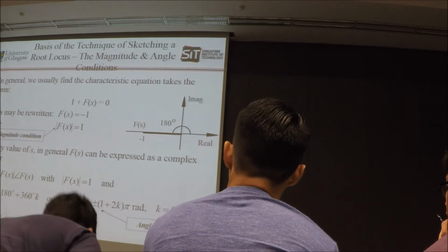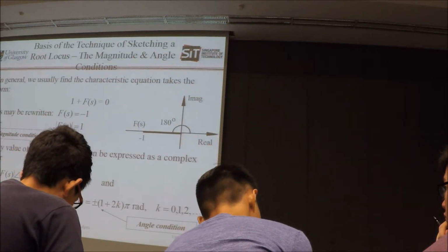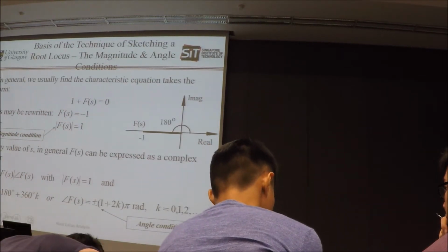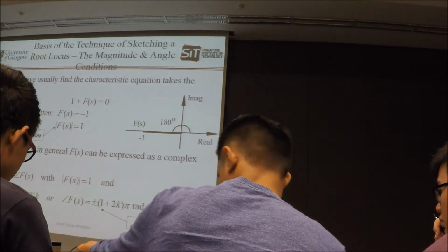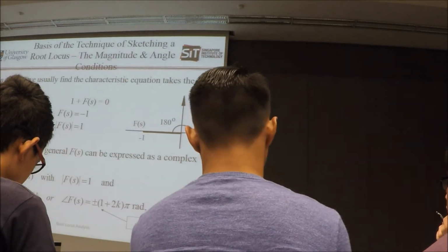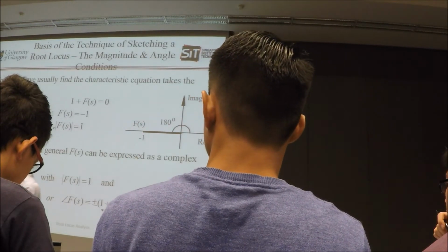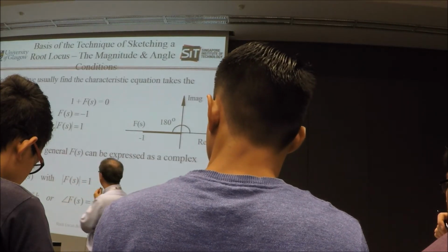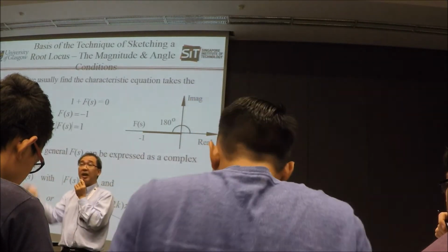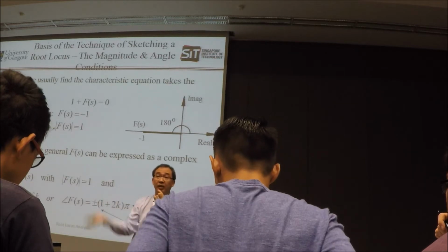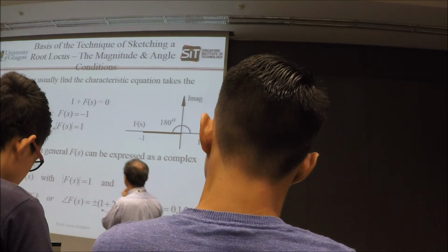As we mentioned, your complex number is similar to your vector. You have a magnitude, and you also have a direction. You need two things to describe a complex number. You can use a real and imaginary part, or you can use your Euler representation, that means the magnitude plus the angle, your polar form. So in this case, minus 1 point in your complex S-plane, what kind of angle does it give you? 180 degrees. The sign convention for your angle is counterclockwise to be positive, so minus 1 point is a fixed 180 degrees.